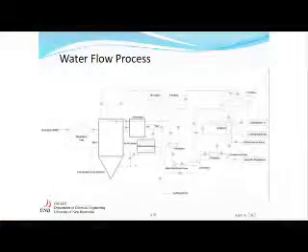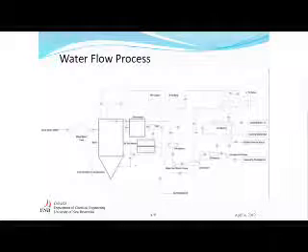And here is the steam cycle. As mentioned in the previous slide, the heat from the flue gas will be used to turn water into steam. The steam will then first flow to the high pressure turbine or the HP turbine, after which it will be sent back to the boiler to be reheated again. The reheat produced will then go to the intermediate pressure turbine, after which it will flow to the low pressure turbine and then followed by the condenser, where it will condense.